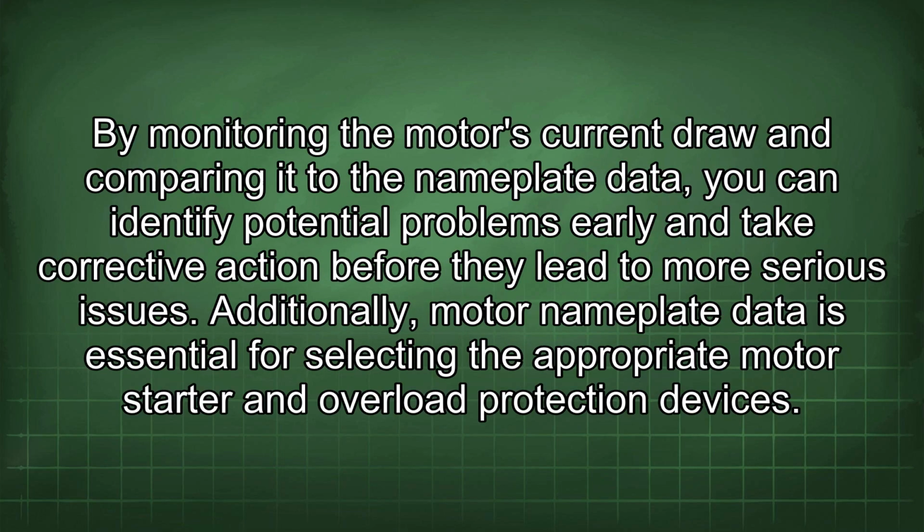By monitoring the motor's current draw and comparing it to the nameplate data, you can identify potential problems early and take corrective action before they lead to more serious issues. Additionally, motor nameplate data is essential for selecting the appropriate motor starter and overload protection devices.